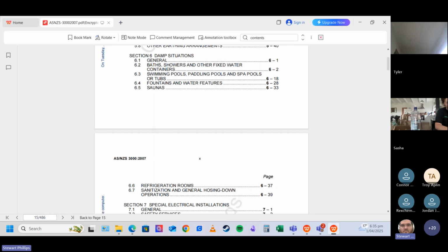So, for example, if you're planning a bathroom installation, you must include correct socket and switch distances from sinks, bathtubs, and showers, ensuring compliance with measurement requirements in Section 6. Electrical fittings in wet areas must follow minimum clearance distances from water sources.